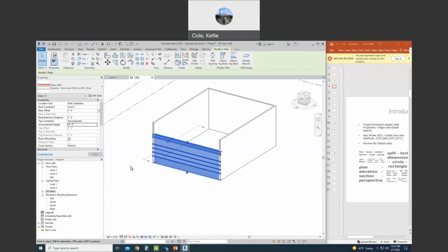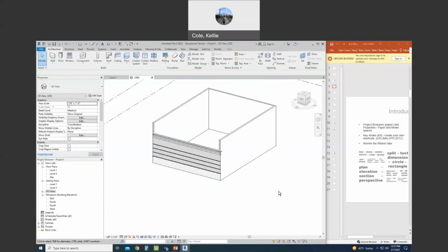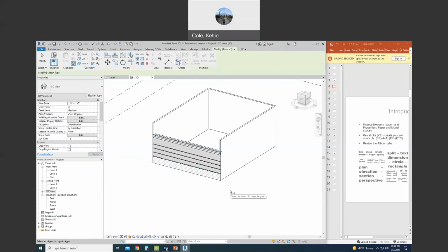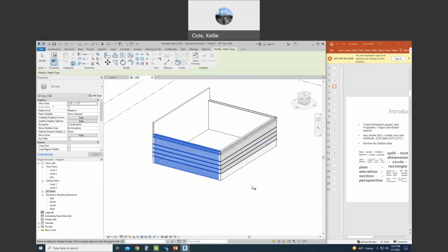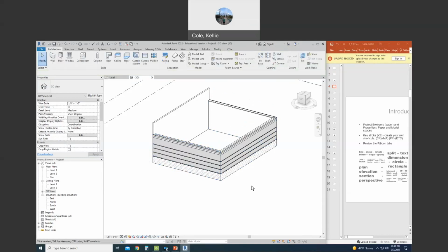So let's say I want 2 other walls in this room that we're drawing to be this brick banded structure. I can use the concept of matching, right? So if I hit escape and type in MA, I'm going to touch the object that I want everything else to look like first, touch it once, and then just click the other walls. So don't do all of them, just 3. To get out of commands, I'm just hitting escape.